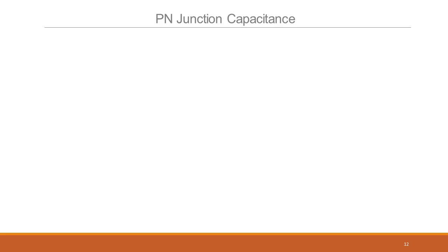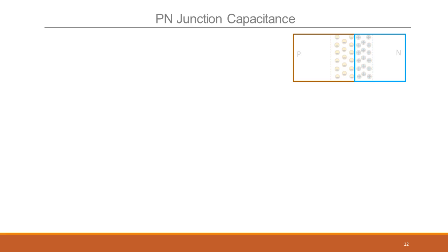So far we have seen a PN junction formed by joining two materials which are P doped and N doped. And when you did that, we had a depletion region formed with the positive ions here and negative ions here. This is the depletion region, and these are immovable carriers. Because of the distribution of positive and negative ions, there's a field from the N side to the P side. Consequently, there was an inbuilt potential with the N side being higher than the P side. We've seen that so far. We also calculated the widths of the depletion region, assuming doping concentrations, etc.